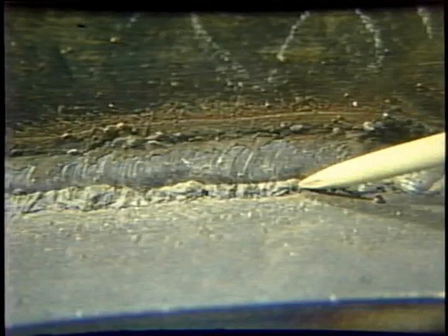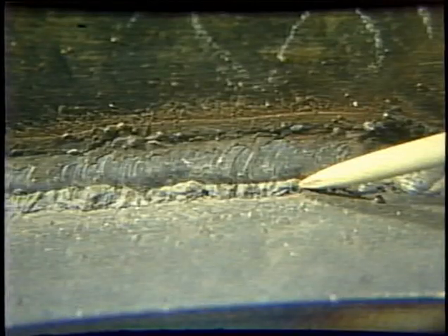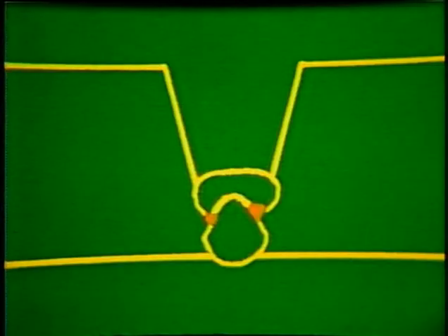A discontinuity similar to porosity are slag inclusions, which are non-metallic solid materials trapped within the weld metal or between the weld and base metal during solidification. Internal slag entrapment is often elongated and generally parallel with the weld axis and occurs between passes or next to the face of a groove weld. This type of inclusion is sometimes called wagon tracks and is commonly found in pipe welds.